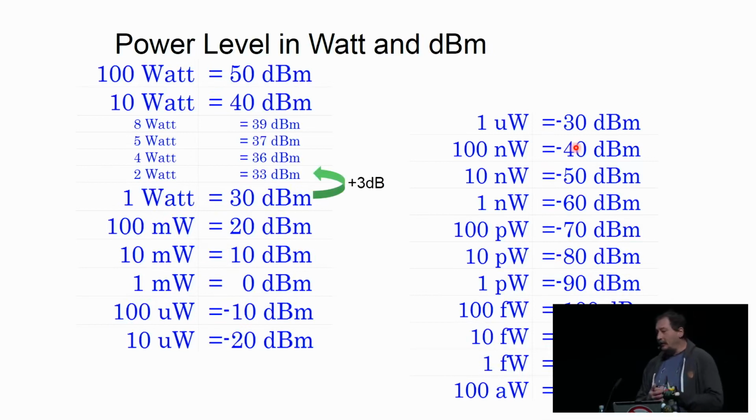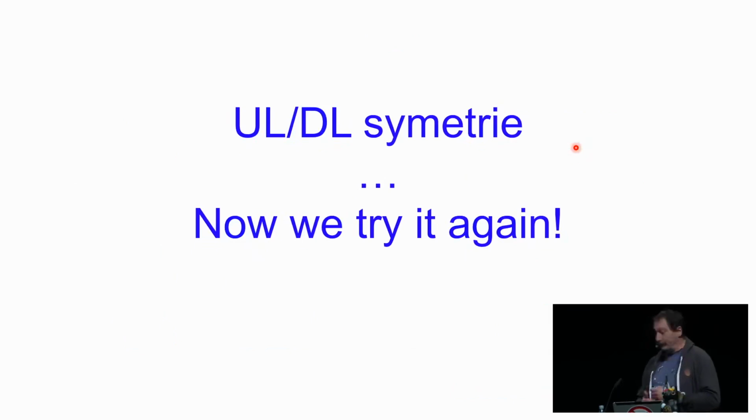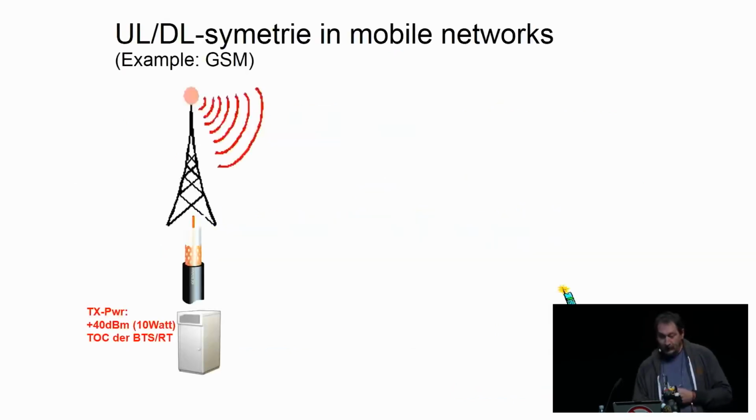So if, for example, I have built an amplifier that has 3 dB amplification, that makes 1 watt into 2 watts, or 10 watts to 20 watts, if it's still capable of that, and it also works in the negative way for attenuation, and so it may attenuate by half. So there are bigger jumps. There are 50 decibels or 100 decibels, and we will use those values when we look at the radiation field. And it gets a little bit more complicated here.